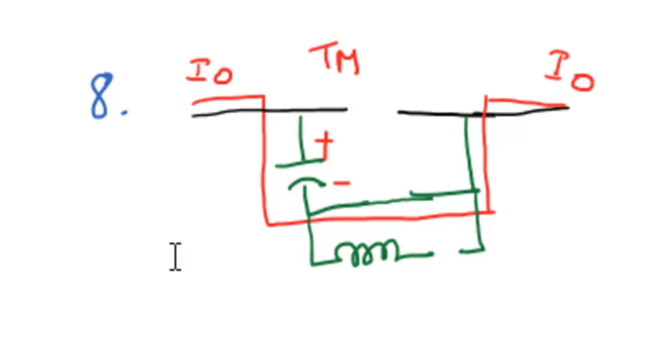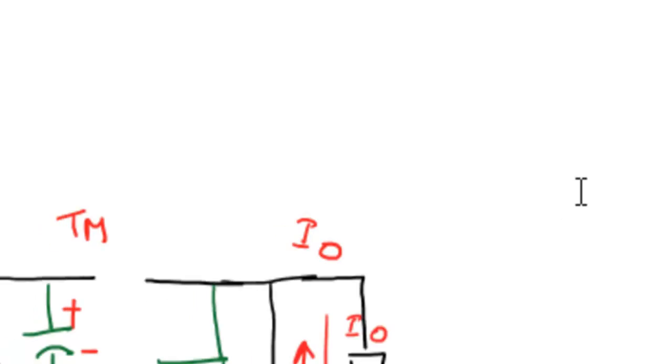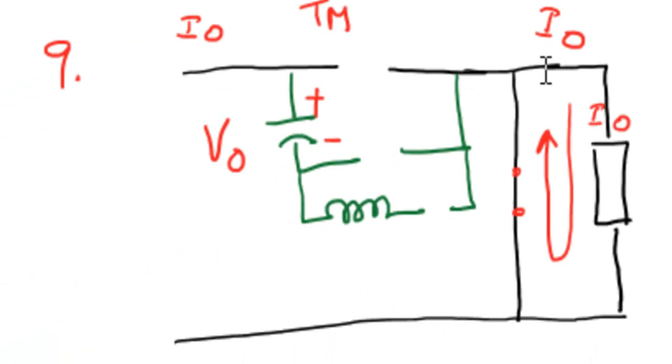That means the source will actually supply the energy to the capacitor as well as the load. So now, in this duration, the capacitor keeps on getting charged by the source with constant load current. Once the capacitor voltage becomes the source voltage, nothing but VDC again, then this voltage and the source voltage, both VDC, are equal. That means the current flowing through the capacitor becomes 0.